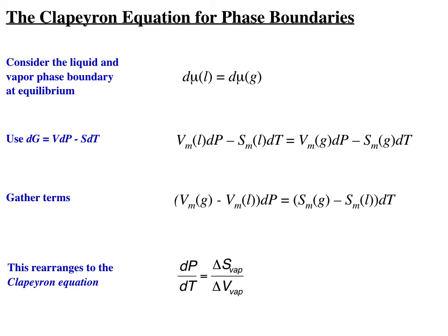And since we can write the chemical potential as a function of the molar Gibbs function, as we have described on the previous several pages for a pure substance, then since dG is equal to V dP minus S dT, dmu is equal to Vm dP minus Sm dT, where the subscript m means the intensive molar quantities representing those thermodynamic quantities. So we will set Vm dP minus Sm dT equal for the liquid and vapor phases.